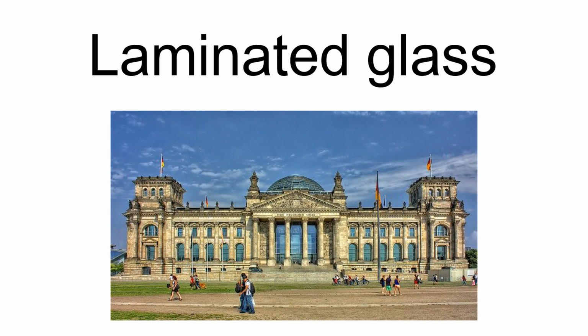Laminated glass is manufactured by bonding two or more layers of glass together with an interlayer, such as PVB, under heat and pressure, to create a single sheet of glass. When broken, the interlayer keeps the layers of glass bonded and prevents it from breaking apart. The interlayer can also give the glass a higher sound insulation rating.